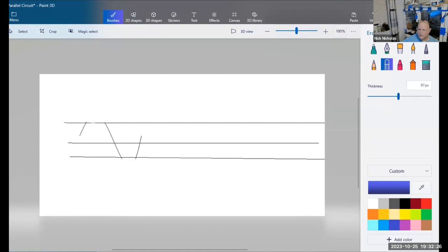And we call this the transistor has flat topped. The signal has flattened out. It goes straight across, DC. When it does this, the transistor will also do some harmonic resonation. It will spit out frequencies you don't want. So not only do you get the signal clipped top and bottom, you get distortion.